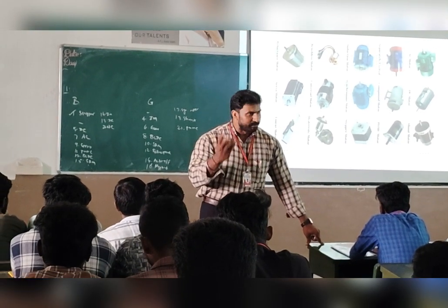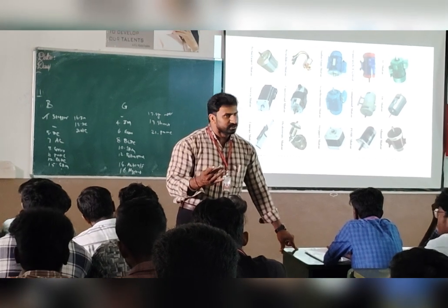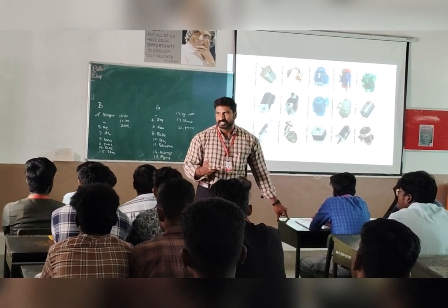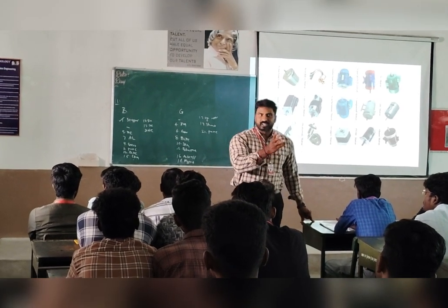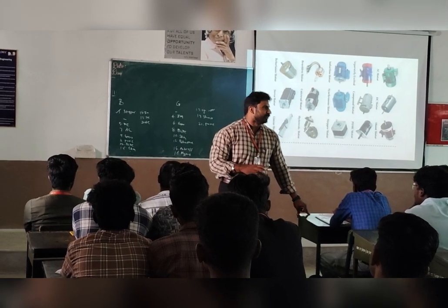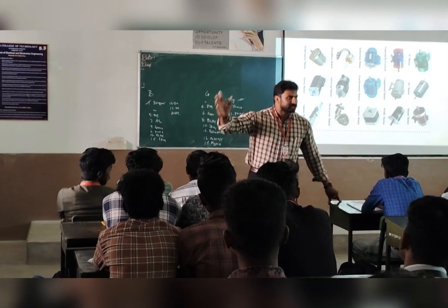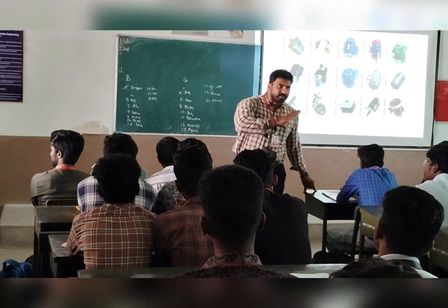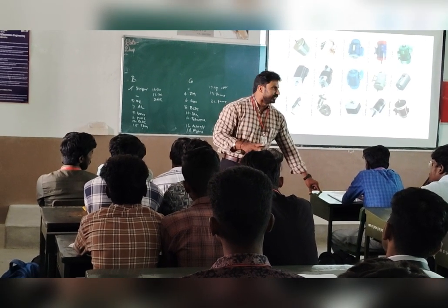For example, the DC coupled motor method, the wound motor method, and the damper winding method. I think you studied it, right? The damper winding will make those corrections. Once the synchronous motor reaches synchronous speed, it will not reduce its speed and will keep running at synchronous speed. That is called synchronizing operation. If I have a motor that should run at 400 RPM without any plus or minus delay, definitely the industry will adopt synchronous motors.